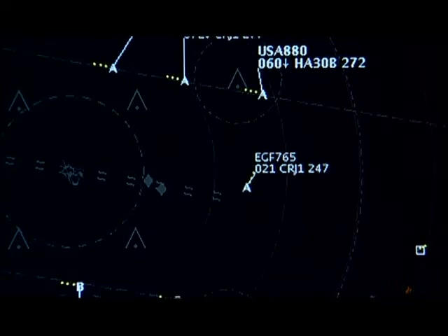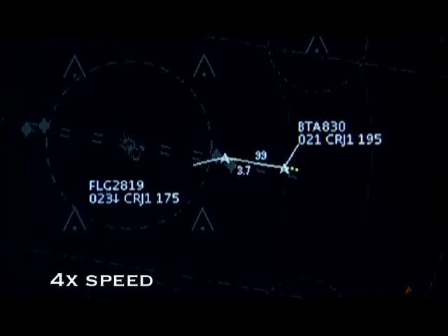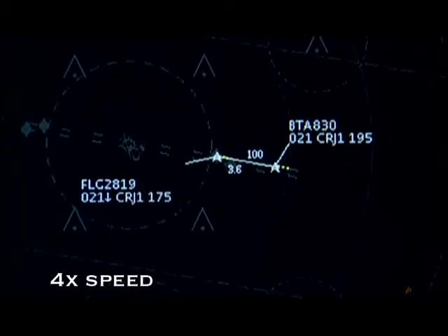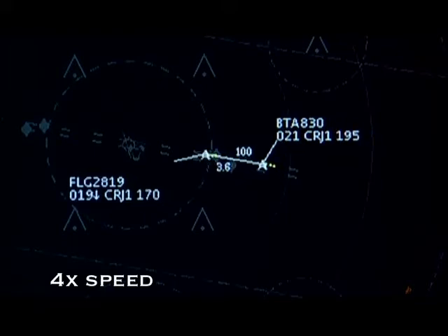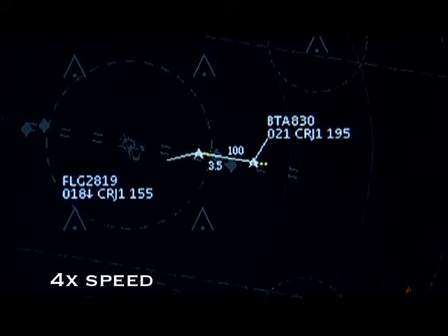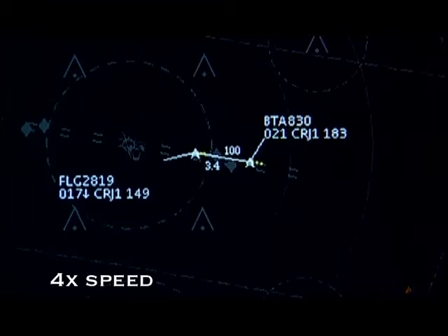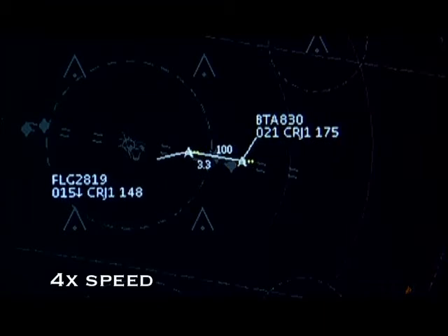And remember that by regulation, civilian aircraft cannot exceed 250 knots below 10,000 feet. Finally, since you know aircraft on final will be slowing down for landing, you must build in additional space behind them to compensate. Jet aircraft will normally begin slowing down about 8 miles from the runway, and will slow down further once they reach the outer marker.